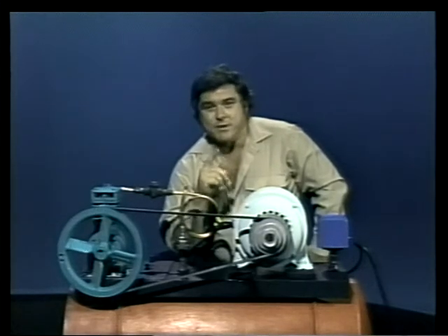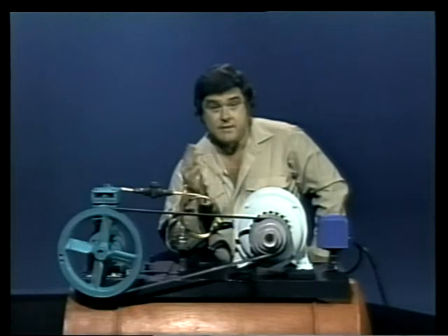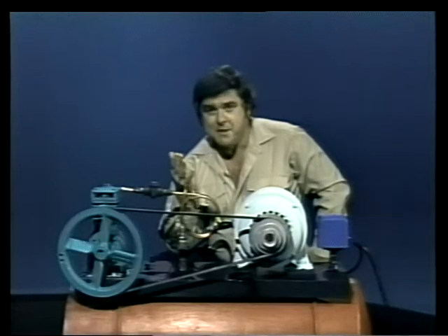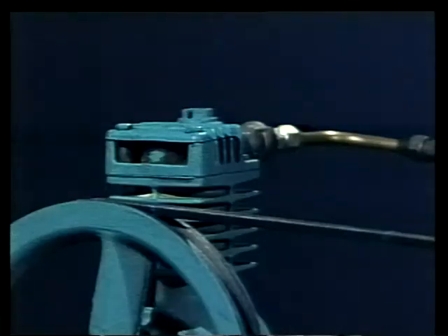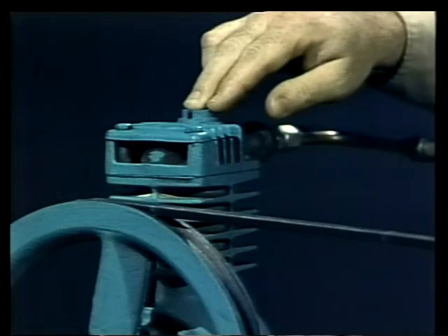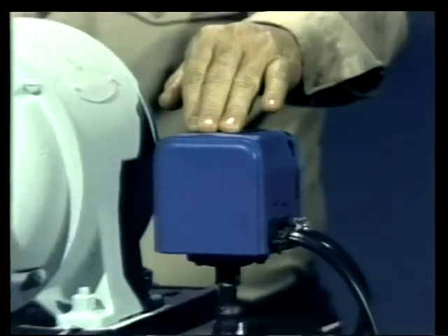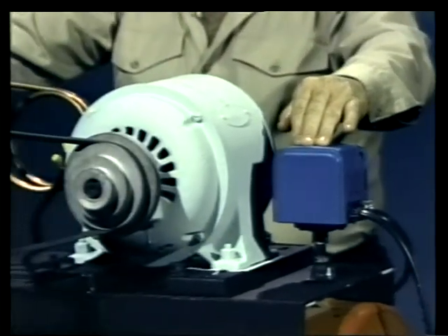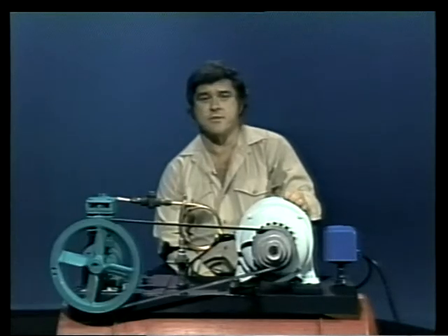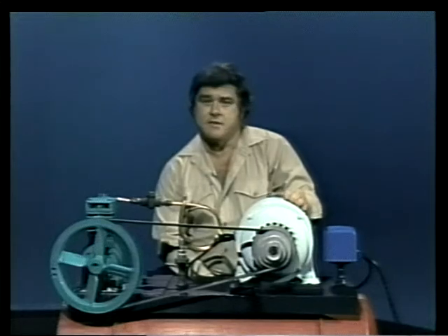The simplest way to control pressure is an on-off cycling control to shut down the compressor when the pressure gets too high, and to start it up again when pressure decreases. That's exactly what happens on this compressor. There's a pressure sensor here. When it senses normal pressure, it opens a circuit and stops the motor. When pressure drops to a lower value, the circuit closes and the motor starts up again, so it'll cycle on